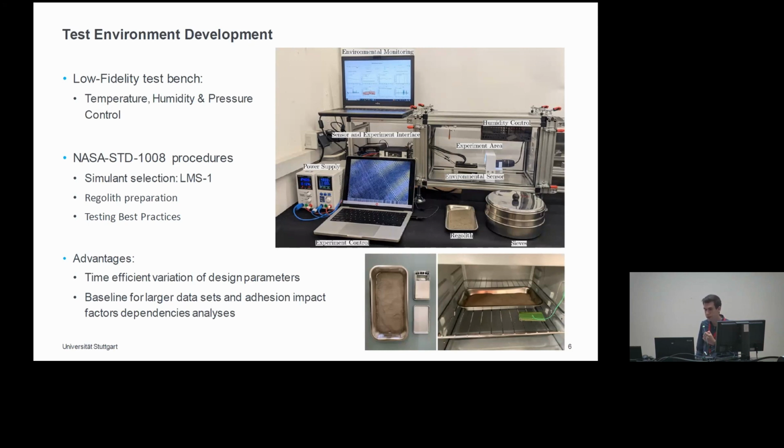The whole setup has advantages in comparison to a high-fidelity test bench. It is very time efficient for testing surface-particle interaction, and you can get a large data set of the adhesion forces and the impact of different environmental conditions on them in a short amount of time, which would not be possible with a high-fidelity test stand, where you have long pump-down times for every test series.